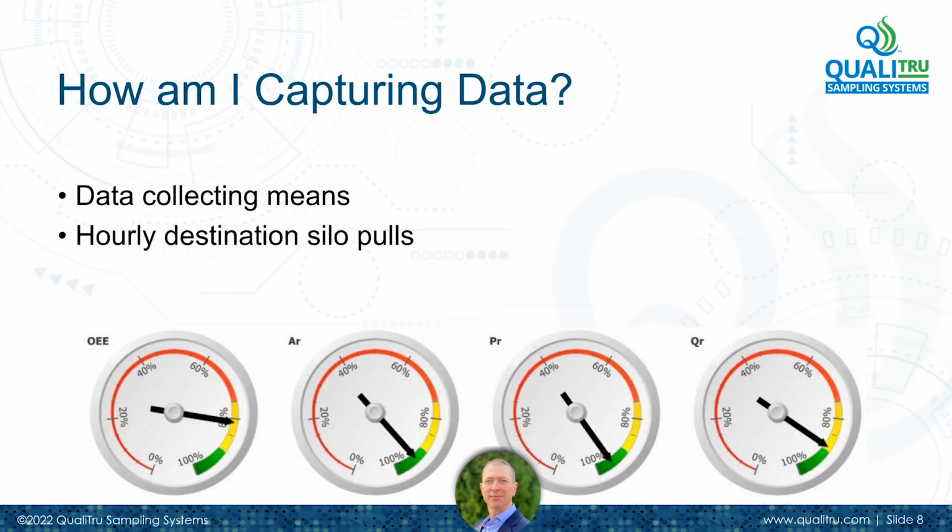Do you pull hourly checks from destination silos along with an inline concentrate? Can you get flagged if a process deviation hits from meters or, say, your inline infrared techniques? Are you getting any artifacts from pulling samples out of spigots that have residue or buildup? Is there time to pull multiple sets of permeate samples, including an end of run set when the baseline is the highest, to look for potential breakthroughs across that filtration layer?